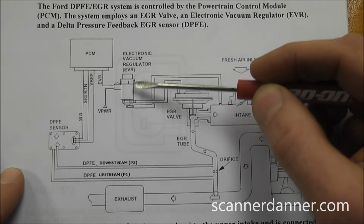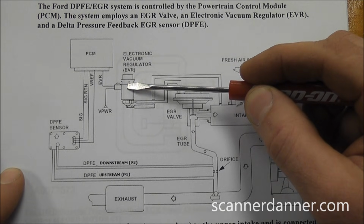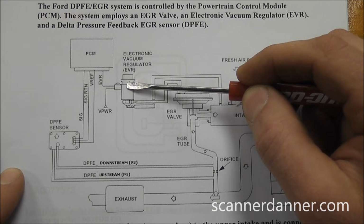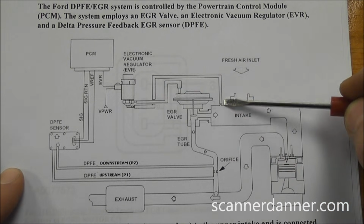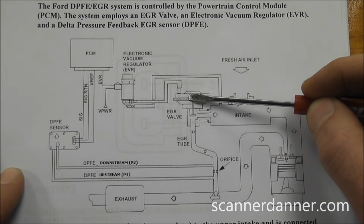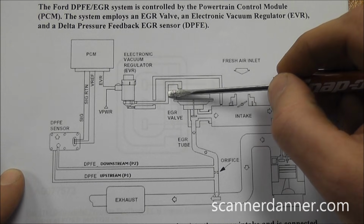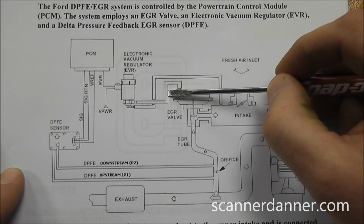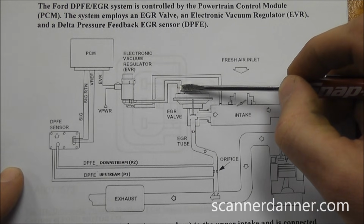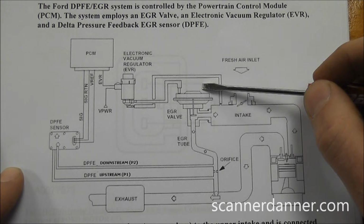So the computer is going to control the pulse width. It's a pulse width modulated solenoid or duty cycle controlled solenoid. Computer's going to control the on time of the solenoid, which controls the amount of vacuum that's going to flow through this to the valve. If we lower the on time, we will lower the vacuum supply to the EGR. If we increase the on time, we will increase vacuum supply to the EGR, and with that, the amount of lift, the amount of valve opening.